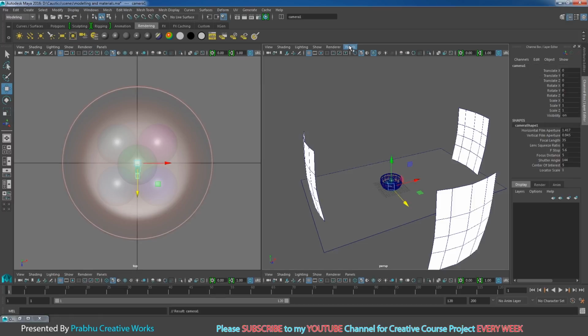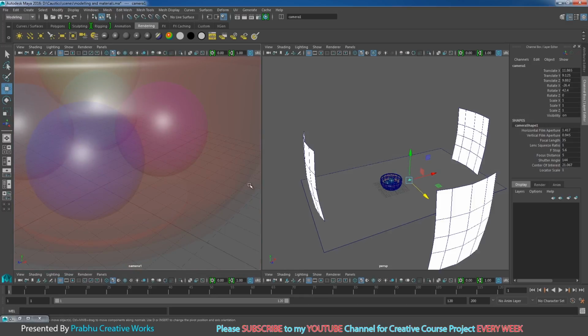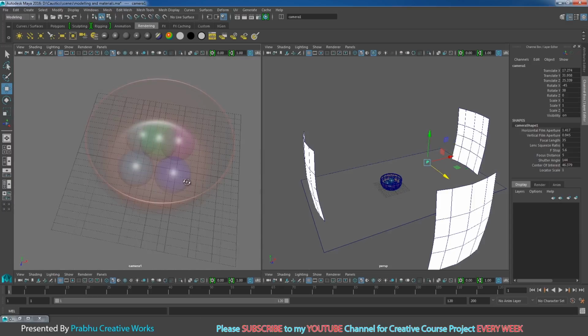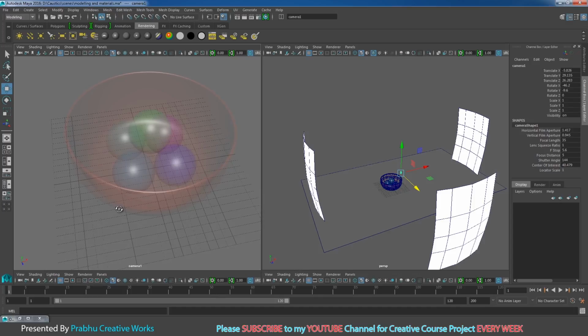Go to panels and choose look through selected. Go to panels and choose perspective and choose camera 1. Now you are able to see through the camera. Now pan the viewport so the camera will be set like this. I want to set my camera view like this. You want to keep X in this direction, Z in this direction. So I will set my camera view like this.